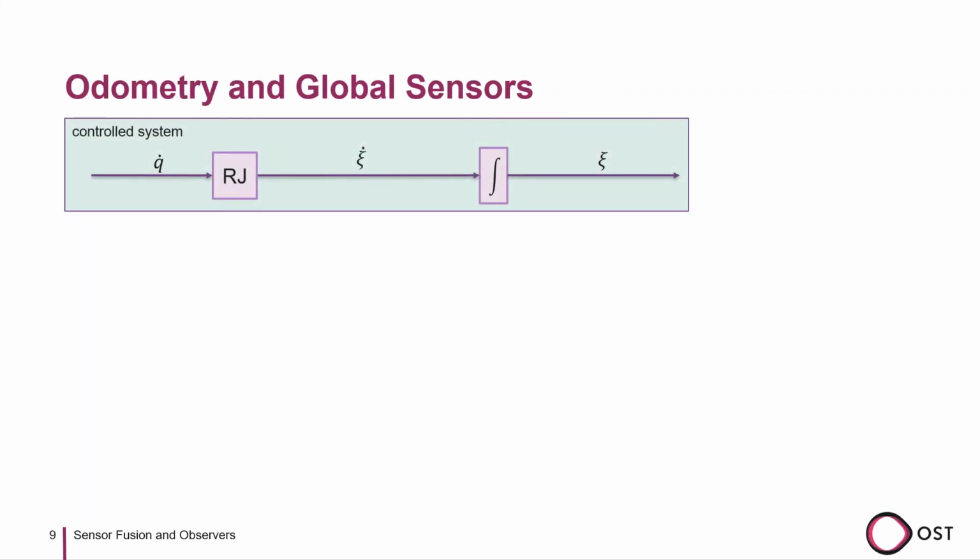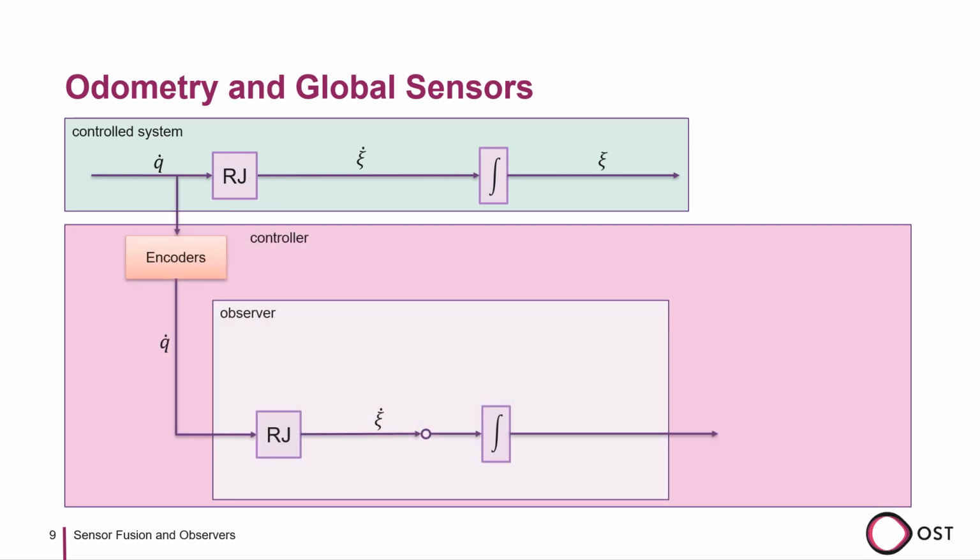So far, we have been looking at different examples for local sensors. However, usually we also want to know the position of the robot in respect to its environment. We can still calculate the global position by measuring the wheel velocities and calculating the global position using the forward kinematics and odometry, but this calculated global position has a drift and offset.